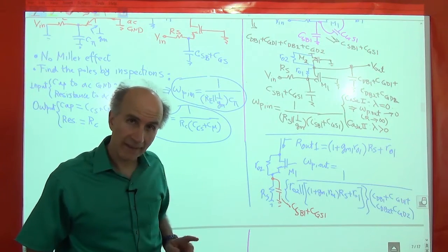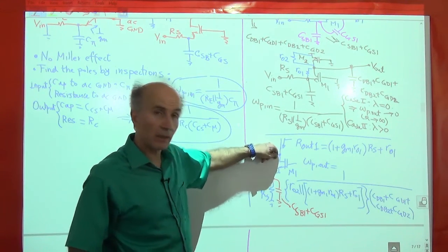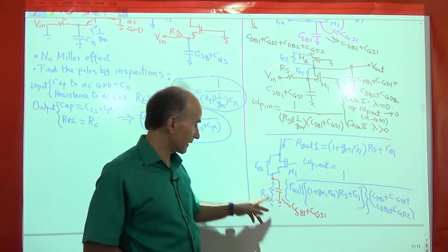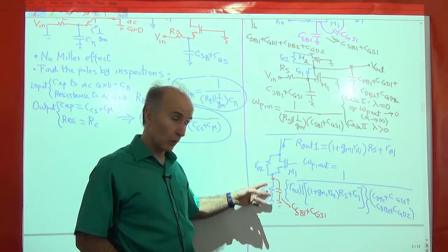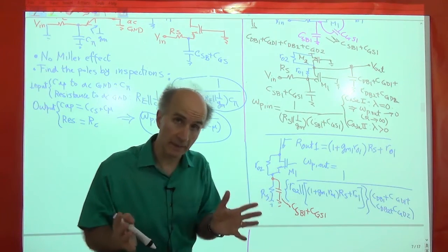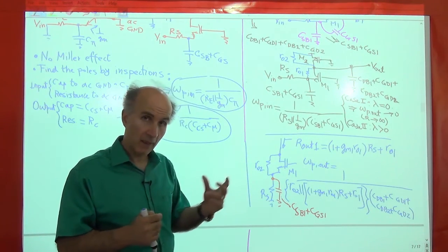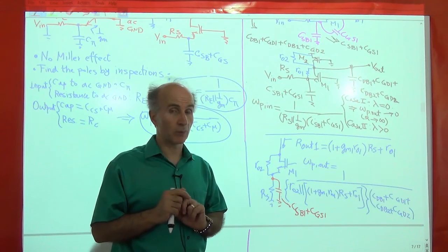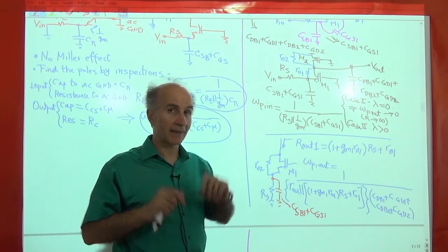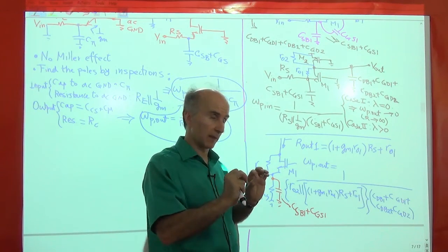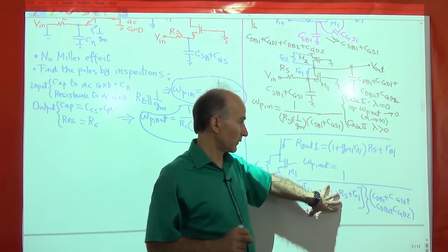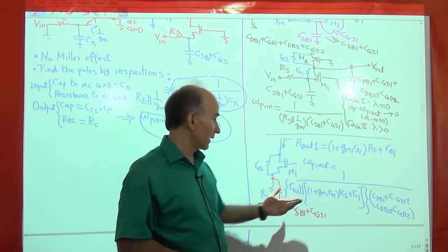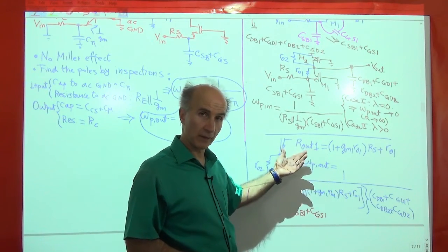So I can't really say that looking down here, I see this, right? Because this capacitance is now in parallel with RS. So what we see here is a general impedance. It's a complex impedance. It's not just some resistance, right? So yes, there's an approximation in what we're doing here. When we say that the output pole frequency is given by 1 over this resistance times that capacitance, it's not quite correct because it's not a pure resistance that we find here.